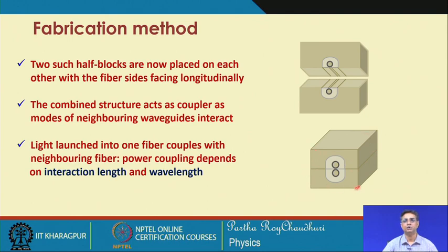But the good thing about this system is the tunability. You can move this hub block with respect to this one in the lateral direction as well as in the longitudinal direction to tune the splitting ratio, the wavelength dependent ratio, and many of the targeted specifications. This flexibility exists because you can give a relative motion between these two.